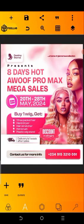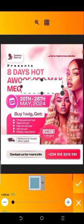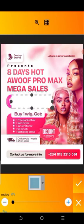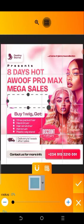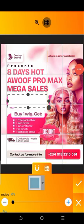Alright, so once that's done, let's work on the shapes next. Make sure this is locked. Alright, perfect. Click on shapes, this third icon, then click on shape, then move this to where we have our grid line. Make sure that this is not clickable, by clicking on this part, right-clicking on it, to make sure it's not clickable. You can see you can no longer move the grid.